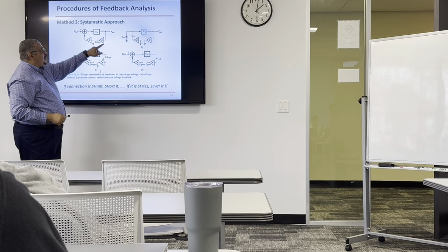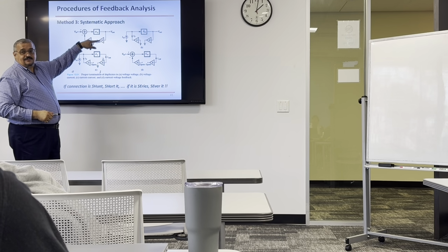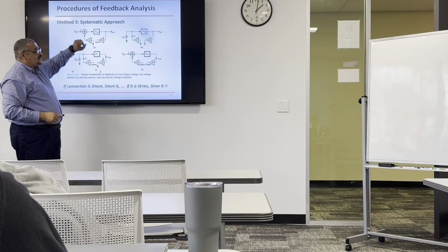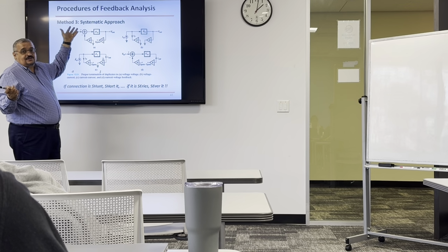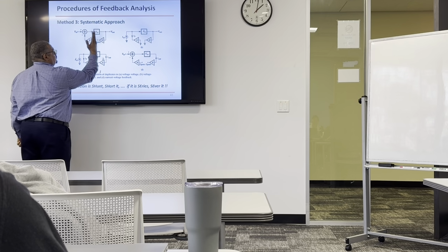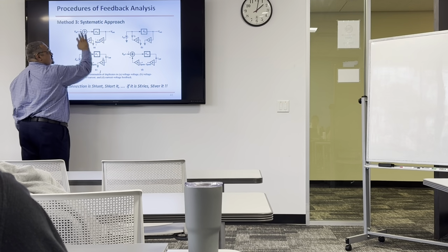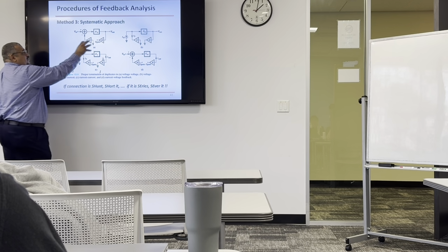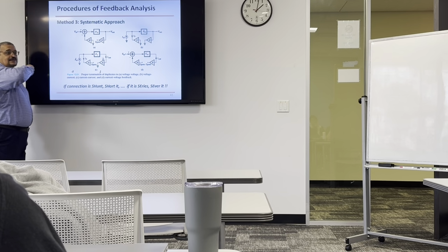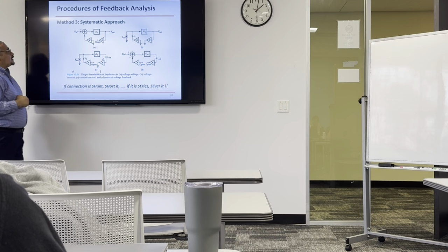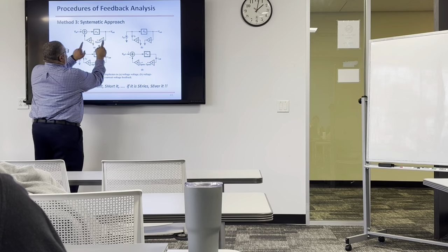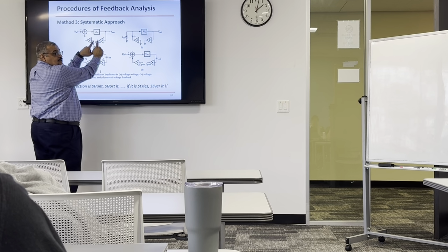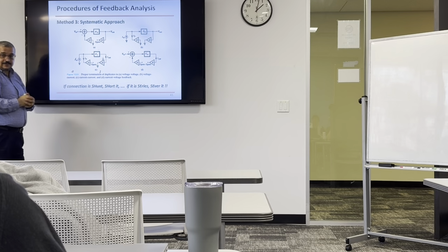But the new amplifier, is it still a feedback amplifier? Because you cut here, right? There's no feedback. When you cut here, this is a new feed-forward amplifier. It doesn't have feedback. But it does have the effect of beta at the output and the effect of beta at the input, right? Now the question: you're going to keep beta connected here. What to do with these two terminals? Should you short them or should you leave them open?